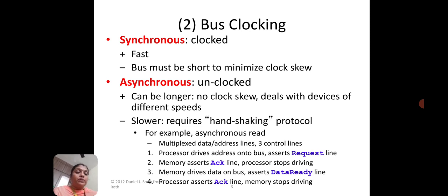Next one is asynchronous bus. If we replace the memory on a synchronous bus with a fast memory, then the memory access time will not improve because the bus clock is unchanged. If you increase the speed of the bus clock to match the faster speed of the memory, then slower devices that use the bus clock may not work properly. So the asynchronous bus solves this problem, but is more complex because there is no bus clock.